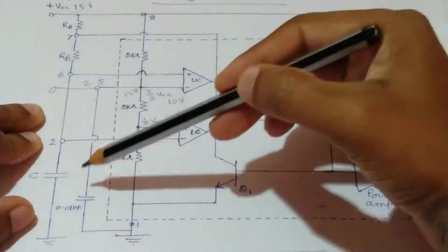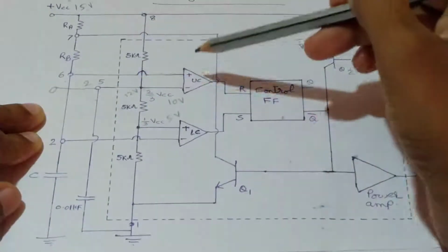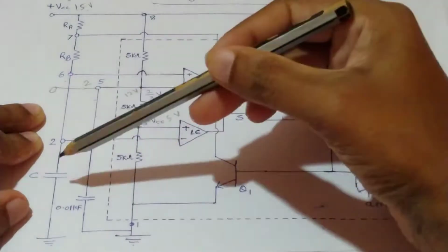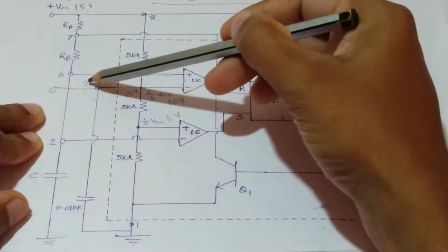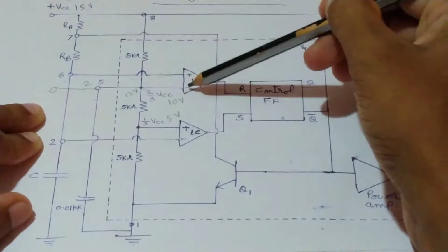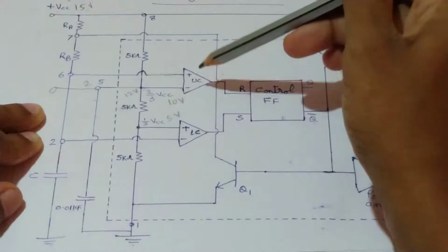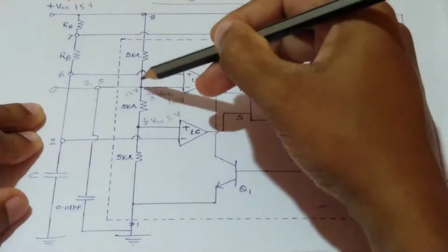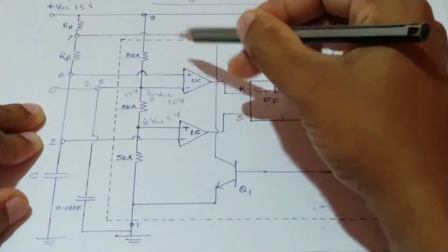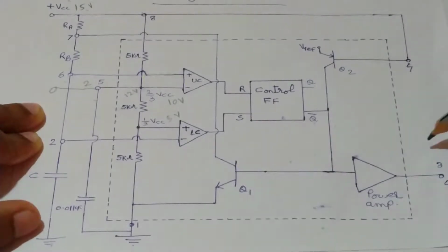So that time duration is increased. When we consider the normal astable multivibrator circuit, this upper comparator triggered when the voltage across the capacitor was slightly greater than 10 volt. But now when 2 volt comes at this fifth pin, the voltage at the inverting terminal is increased to 12 volt, and now this upper comparator will trigger only when the voltage across this capacitor goes above that 12 volt. So that time duration is increased, and hence the time in which the output remains in its high state is also increased, and hence the width of the pulse is increased.